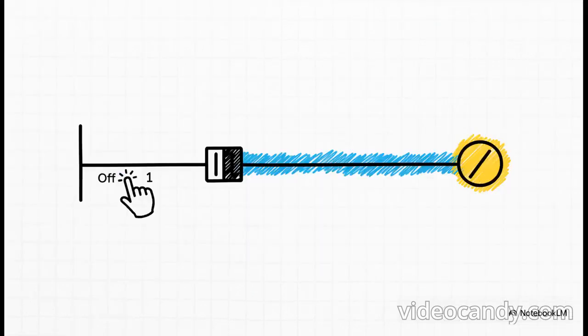And this is the magic moment, the payoff for all that setup. Right inside Studio 5000, while you're online with the emulator, you can actually right-click your input tag and just toggle the bit from a 0 to a 1. The instant you do that, you'll see the logic go green and your output bit will immediately fire on. You've just run your first PLC program on a completely virtual rig.